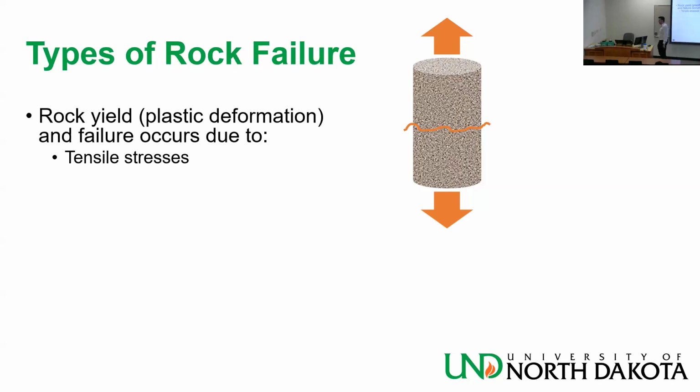We're going to talk about it later, but for that to happen, we sort of introduced it before, it is basically this. T is the tensile strength of the rock, what holds the rock together against tension. And sigma 3 is the least compressive stress applied to the rock, i.e. the most tensile. Least compressive, most tensile.